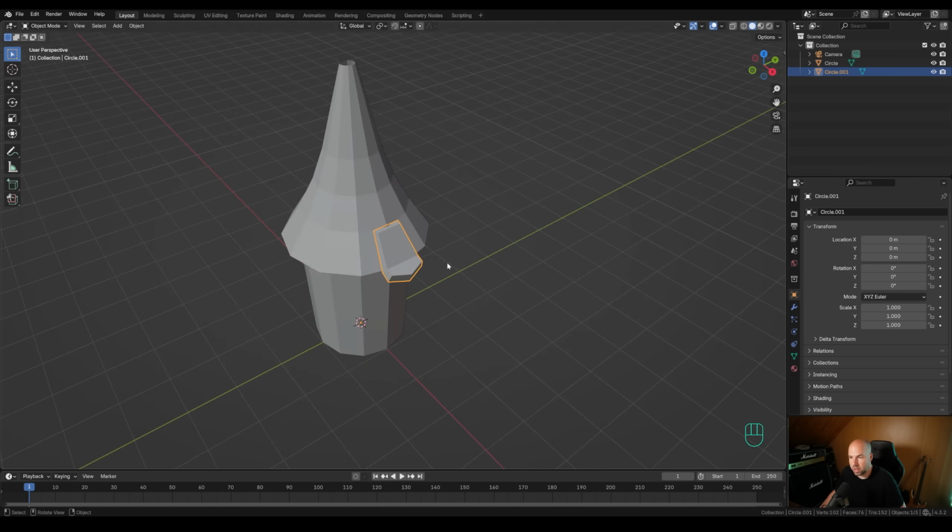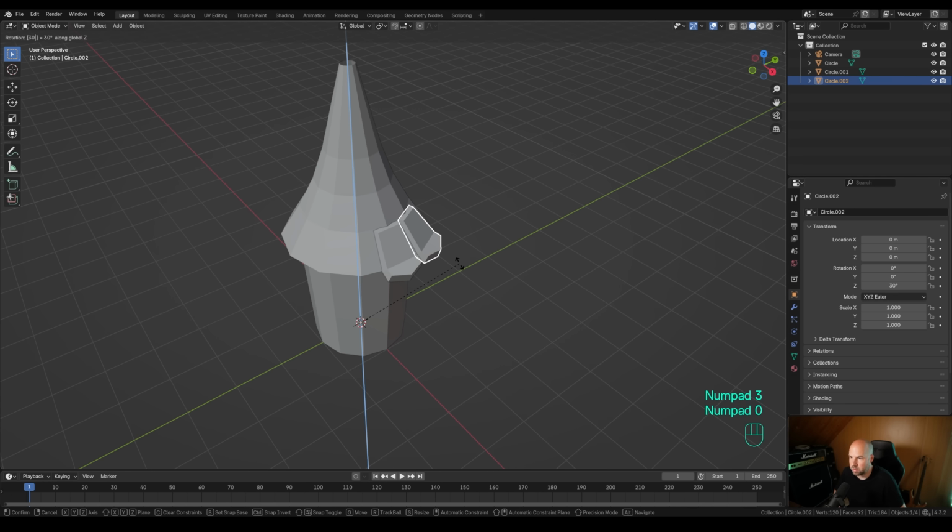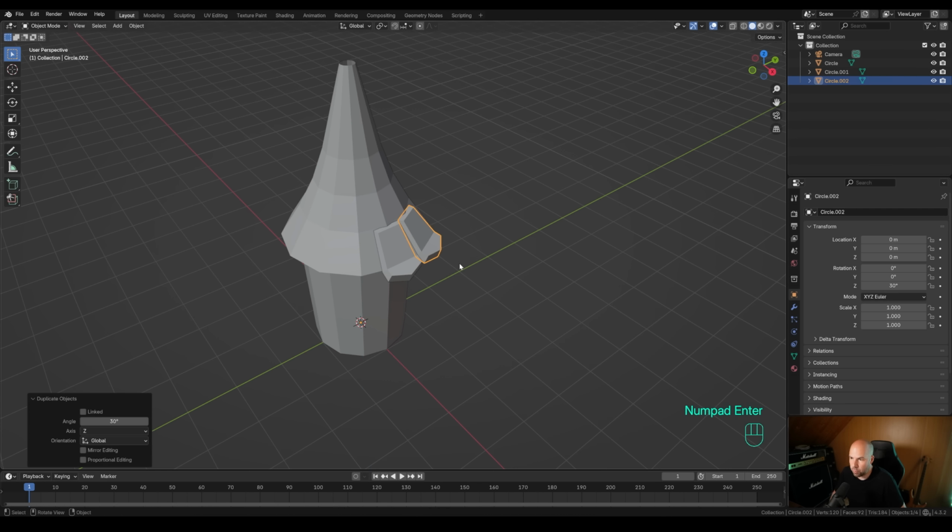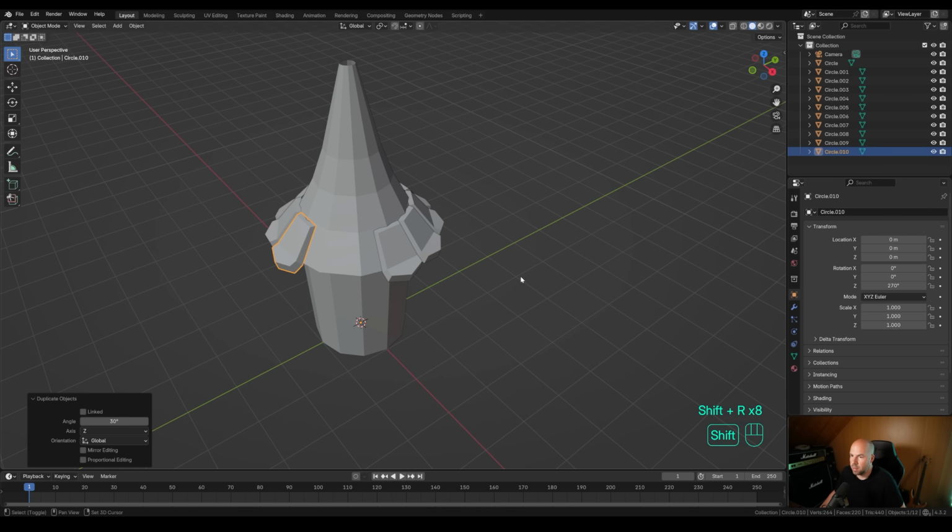And now in Blender you can chain some of the commands, so just repeat this really carefully so you don't interrupt this chain of commands in any way. So first we'll press Shift D, then immediately R and Z. So we duplicate it, rotate it around the Z-axis, now enter 30 to rotate 30 degrees and press Enter. And before you click or touch anything, let's just press Shift R and you can just repeat the whole chain of commands to create a circular array like this without actually using the array modifier.